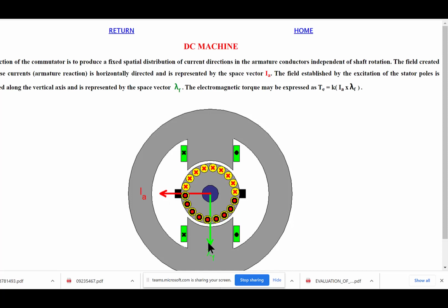If I ask an exam question, what are the two types of windings that you generally see in machines? It's field and armature. It's not stator and rotor. It's not three-phase. It's armature and field. Armature generally is related to the torque producing part. You can change the torque production by changing the field, but as you draw more current, you're producing more torque, or you're drawing more torque.